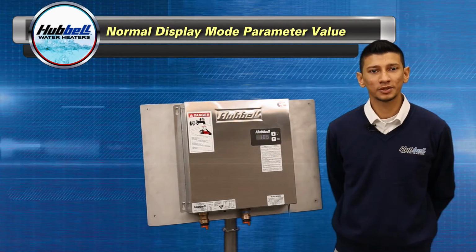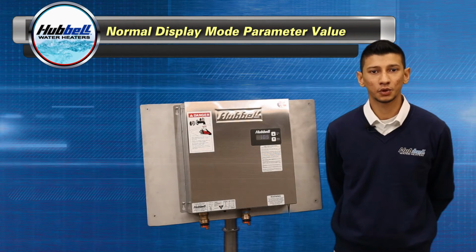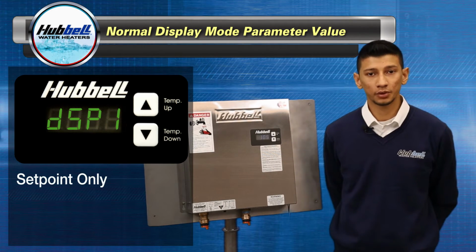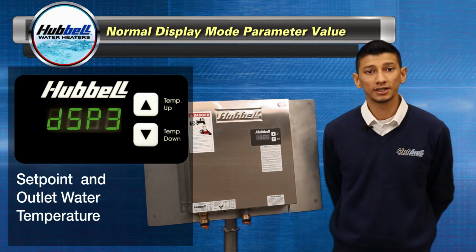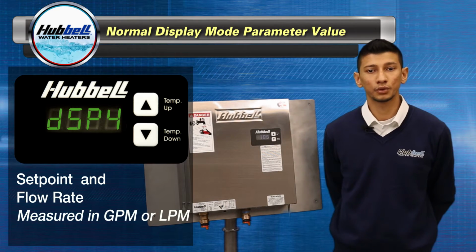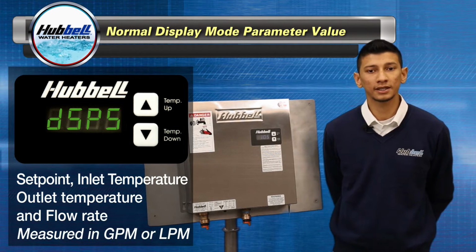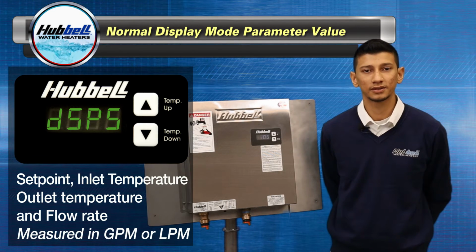Next, we'll select the normal display mode parameter value. This determines what is shown on the display during normal operation and standby. There are 5 to choose from. DSP1 shows a set point only. DSP2 shows a set point and inlet water temperature. DSP3 shows a set point and outlet water temperature. DSP4 shows your set point and flow rate, which is measured in gallons per minute. DSP5 shows your set point, inlet and outlet temperature, and flow rate, which is measured in gallons per minute.